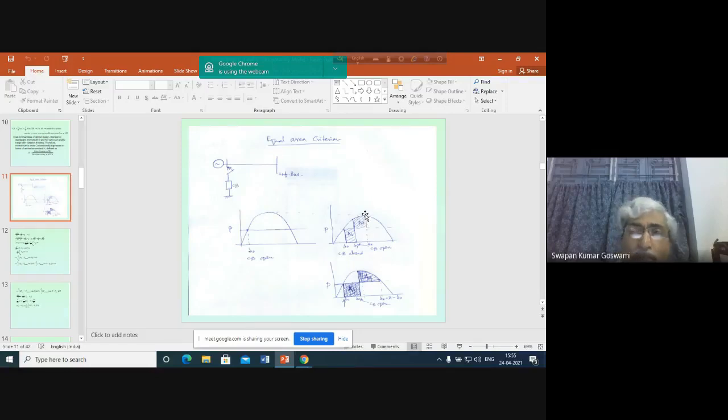Speed will be again the synchronous speed. So if two such areas are available before this point is reached, then we can say that the system or the generator will be able to maintain synchronism, maintain stability. Here we have created a situation such that this area A4 is actually completed just at this angle delta 2, where after this position is crossed, again input becomes more than the output power and speed becomes again above synchronous.